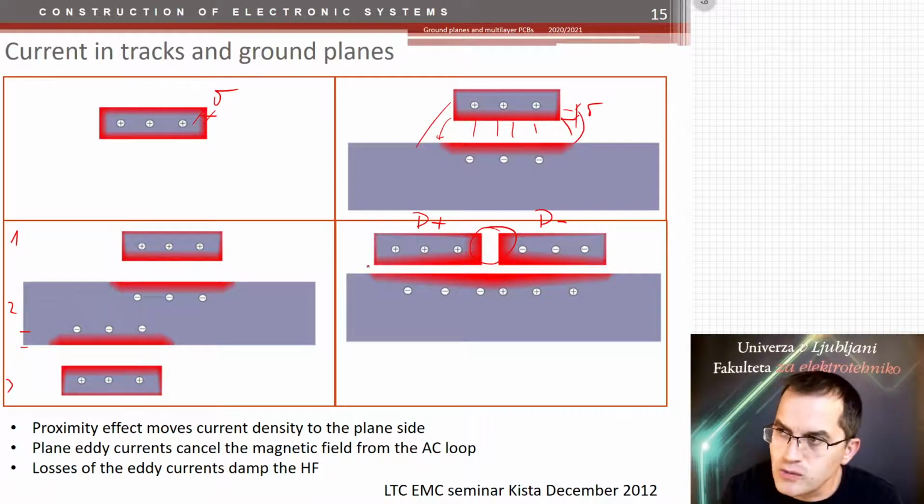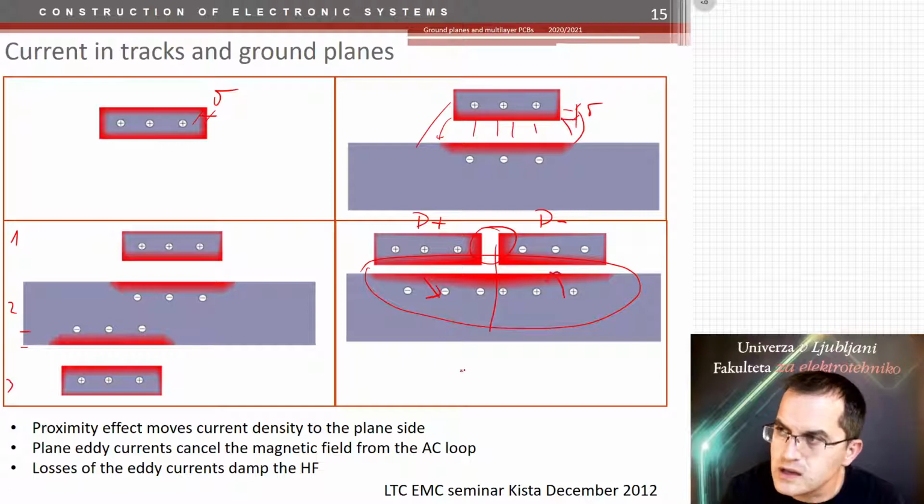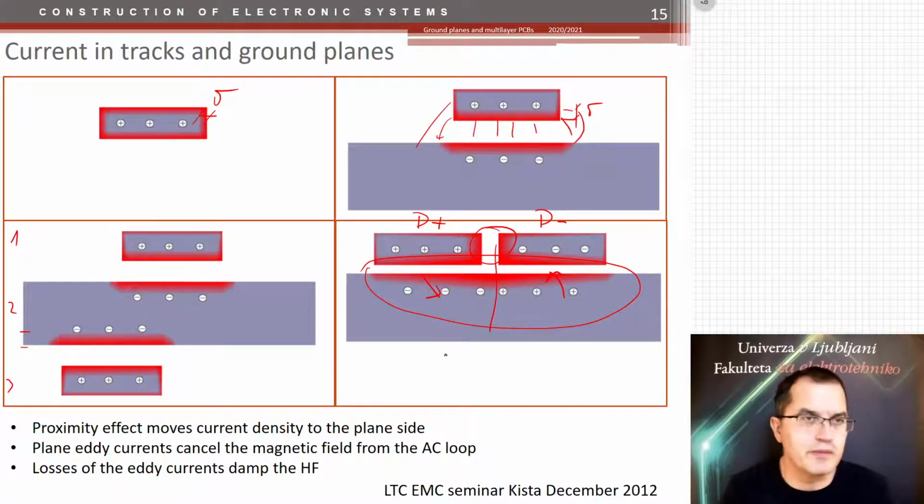The common mode part is in general almost zero as a total, but looking at each half, you would see that you have a current flowing here, one flows out and that one flows in. So we have actually two current components just below each track separately, and for those current components you have to keep the ground plane still there. So also differential signals need a ground plane.